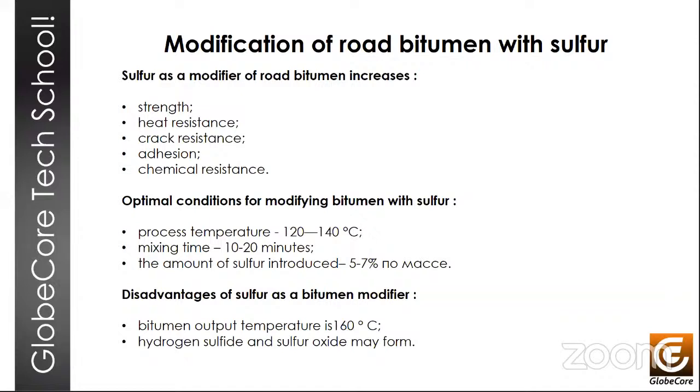So it was found that when sulfur is heated to 180 to 220 degrees centigrade, harmful gases are in fact emitted. While if the temperature is reduced to a range of 120 to 145 degrees centigrade, and if the sulfur content in the mixture does not exceed 20%, then there is not much danger of such release that would exceed the sanitary norms and health standards. There is also the increased corrosion of equipment compared to the conventional technologies. That's something to be mindful of.